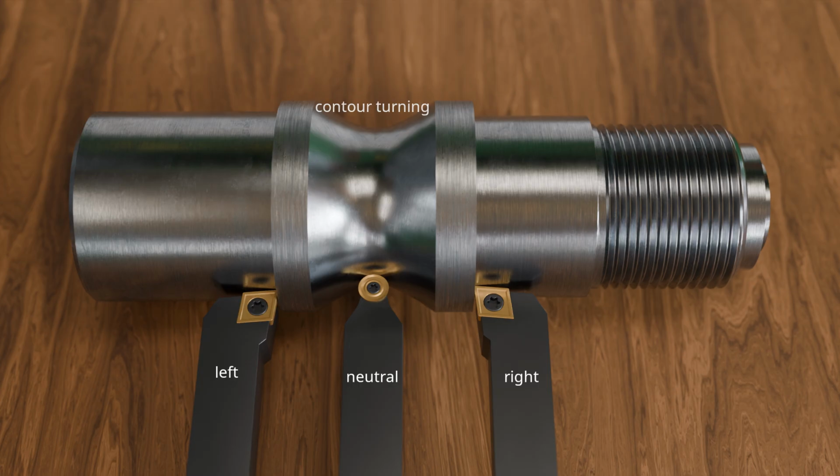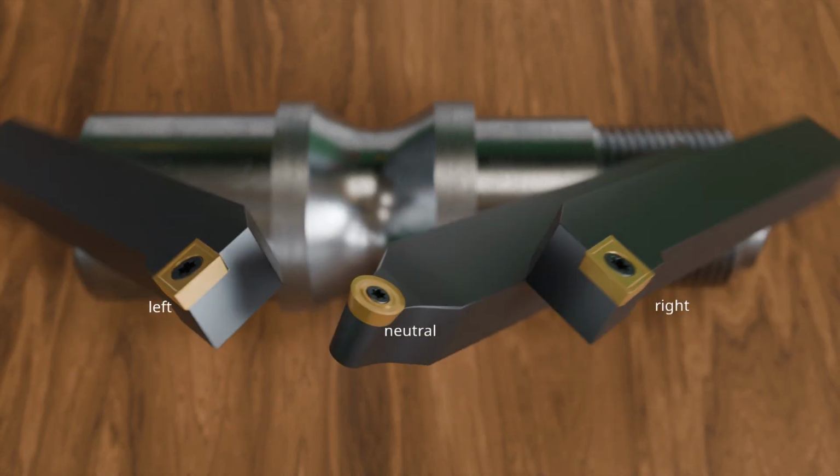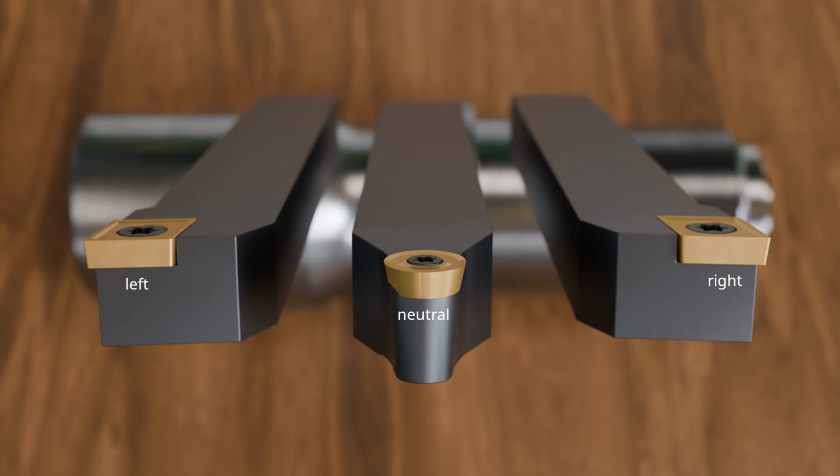The designation depends on which side the main cutting edge is located relative to the tool holder when viewed from the front. If the cutting edge is on the left side of the tool axis, it is called a left turning tool. Conversely, if the cutting edge is on the right side of the tool center, it is called a right turning tool.